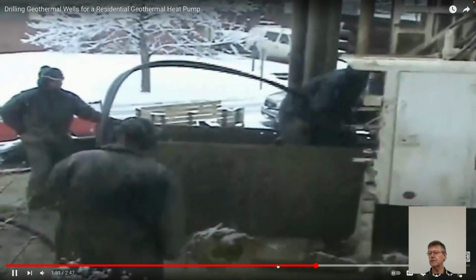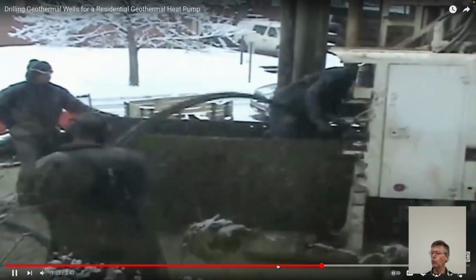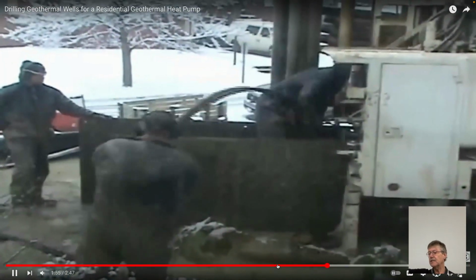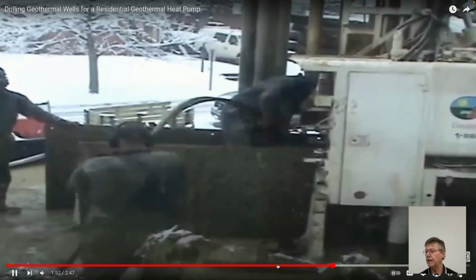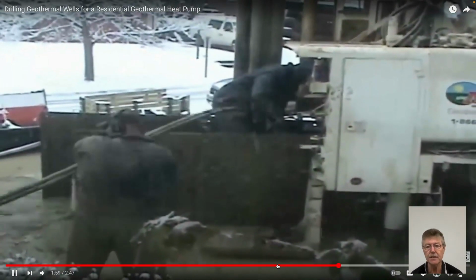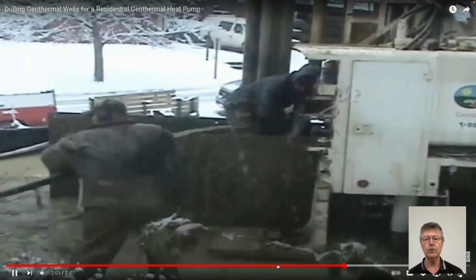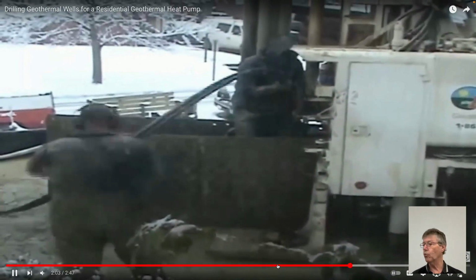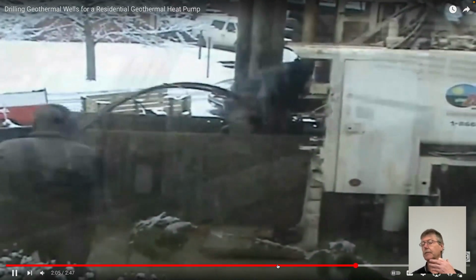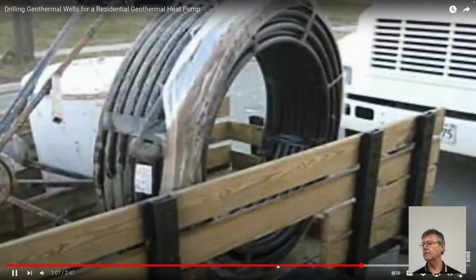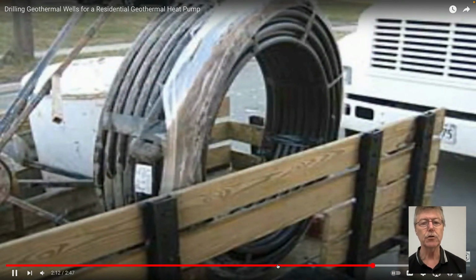And so that will act as a heat exchanger, pumping warm water, say 20 degrees centigrade water down. It'll pick up enough cool as it circulates into the subsurface to cool down that water that's 20 degrees going in, comes out at 10 degrees, and then you use it in your house to be super efficient in terms of heating and cooling.